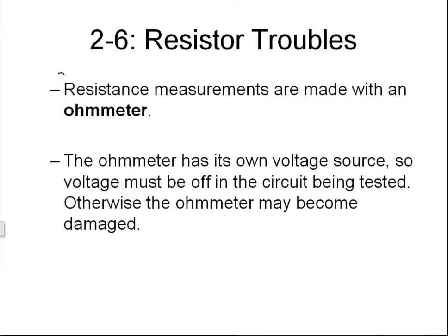We measure resistors with an ohm meter. So an ohm meter has its own voltage, so you got to cut off voltage and generally isolate the circuit you're measuring from anything else. And as an example of that,